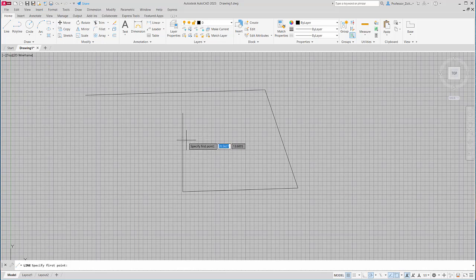And you'll notice that when I go over top of the line, it's got a green box. What is that? That's the default setting that is a snap position. So what does that refer to? AutoCAD works to 16 decimal place accuracy, which is extremely accurate. And one of the functions it gives us is to be able to identify the end of the previous line to that accuracy level. Now you can see my cursor, that's the cross, is not on the actual end, but just over top of the line.